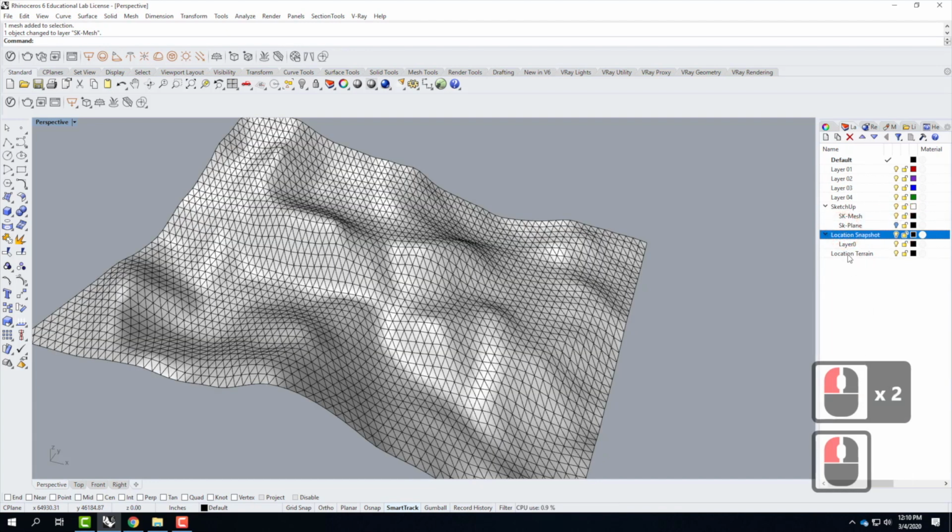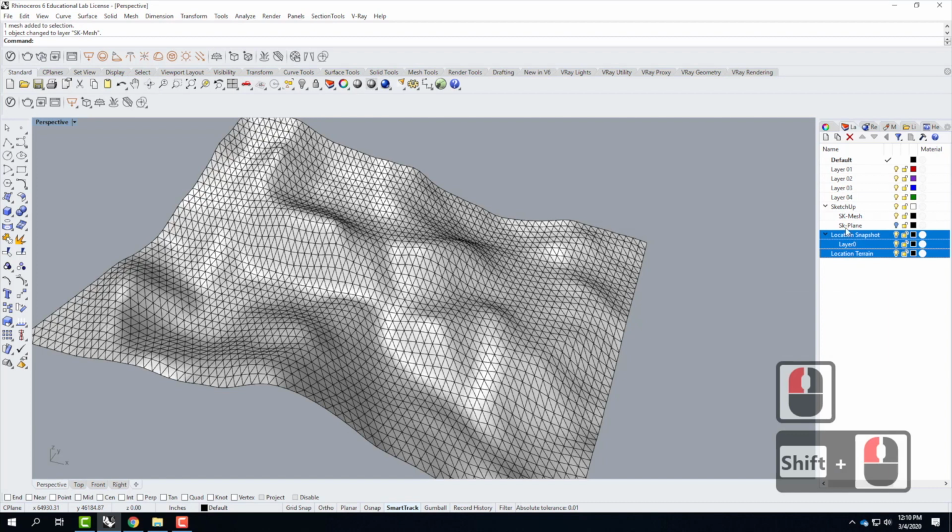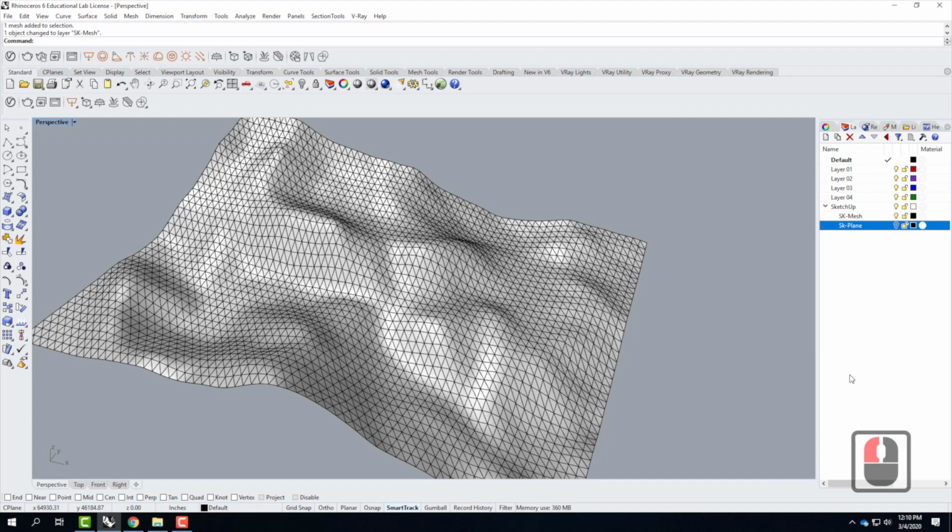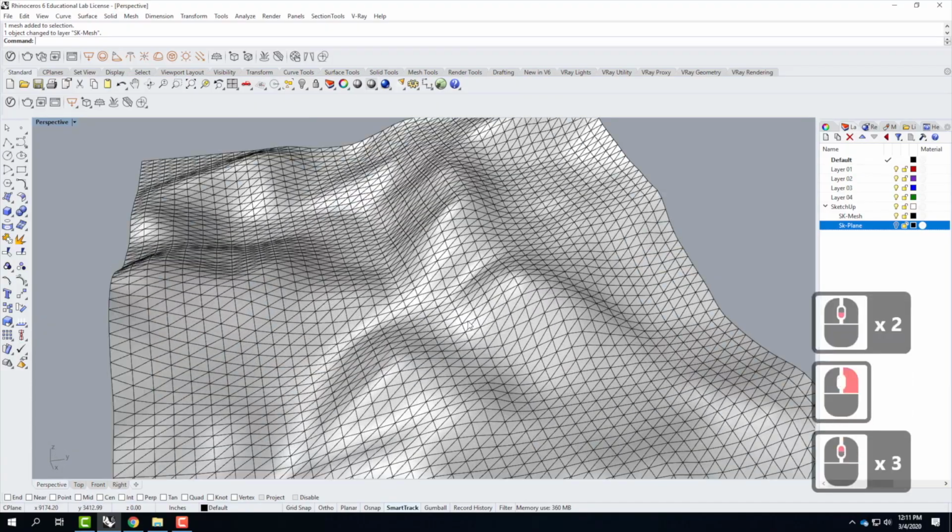At this point, I can go ahead and delete all the rest of the layers that came in with SketchUp. So we'll just click on delete. If yours don't delete, it's possible that you didn't delete the little person. If you didn't delete the little person, you have to go find that person and delete them. It also might be that the person is a block reference, so you have to delete the block reference to delete the layers. It's not the end of the world if the layers stick around for right now. Ultimately, you'd want to delete them for a cleanliness factor.